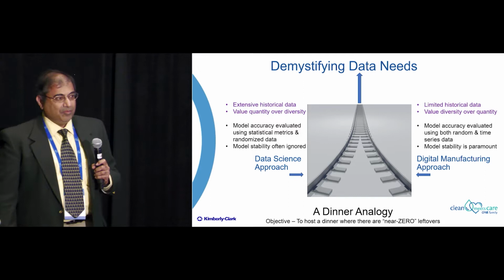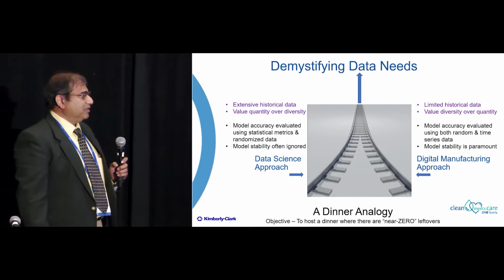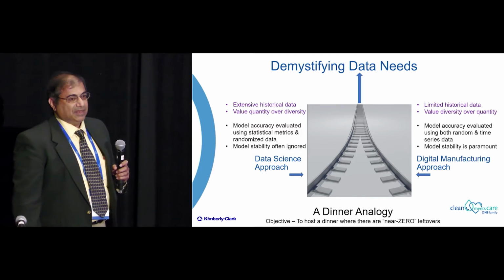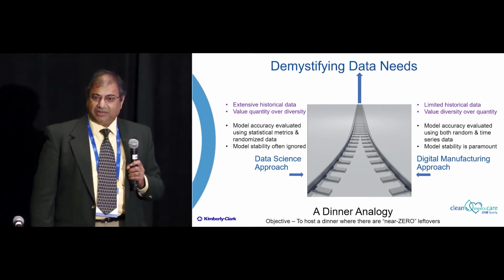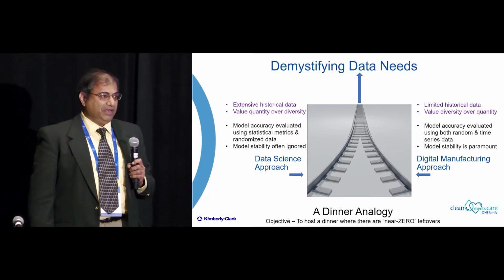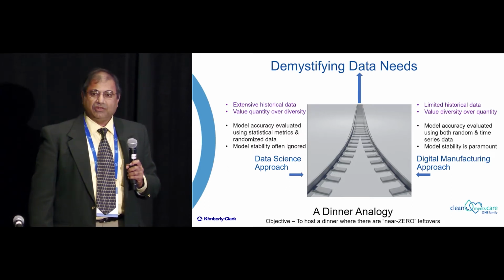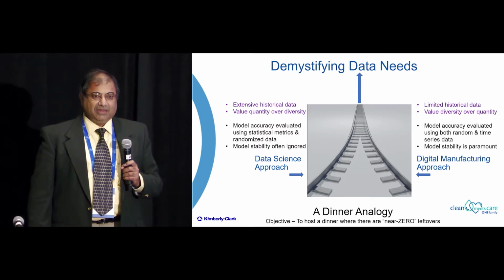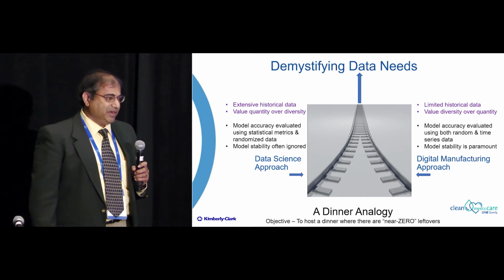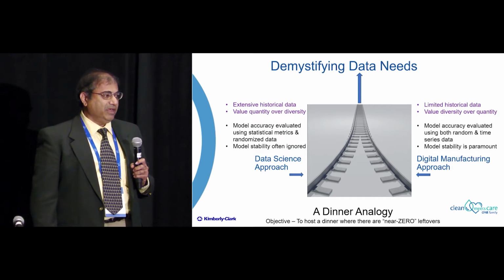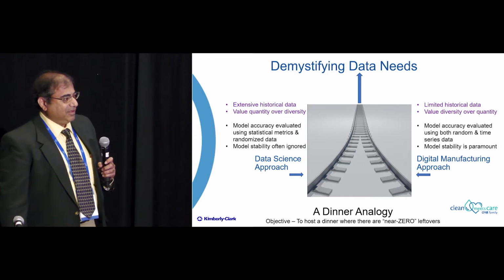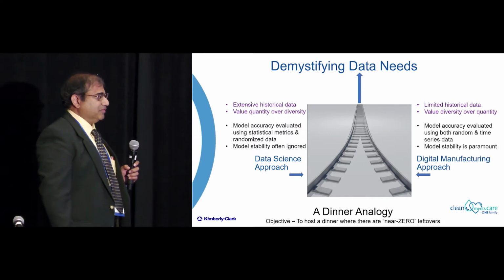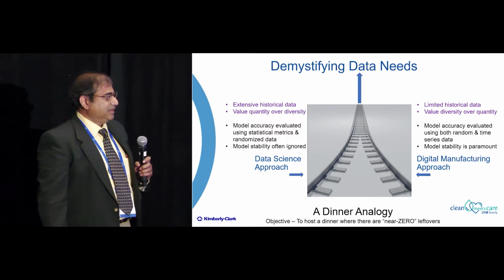But what I often find more important is time series testing, because the value of time series is you can look at the predictions and you can now go and pull data from your historian and you can match things up. And you can sit down with a process expert or a subject matter expert and you can try to figure out why things don't look right or confirm that they do look right. Random evaluation by itself misses that element.